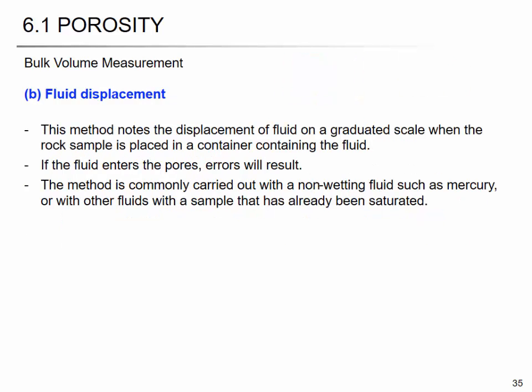So then, what do we use? We can use fluid displacement. You have a graduated cylinder and you put the rock core in, right? Then you have an increase in water volume or fluid volume, and this gives you the bulk volume.